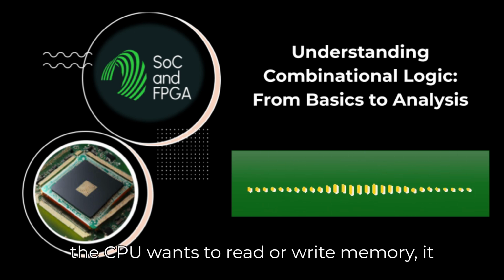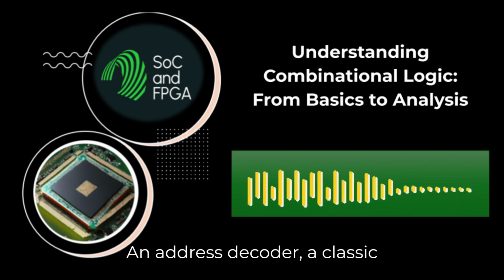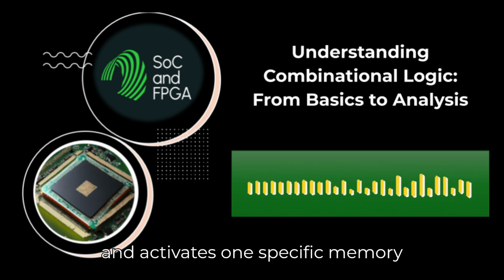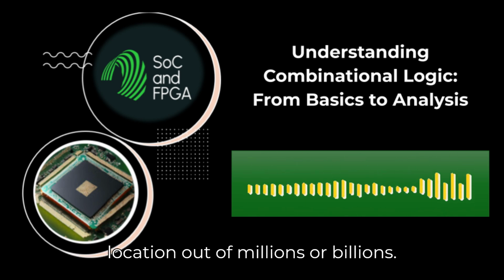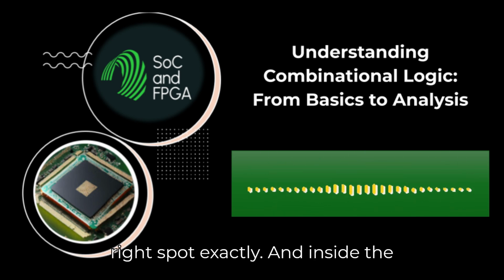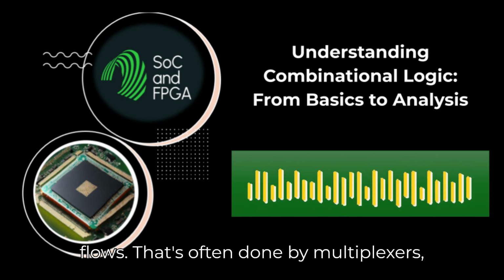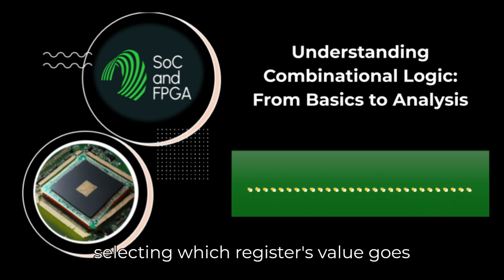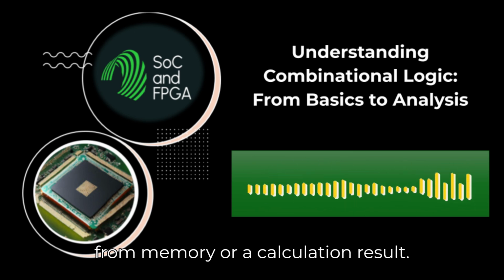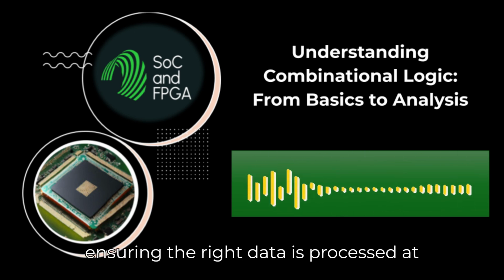And getting data to and from memory. When the CPU wants to read or write memory, it puts a binary address on the address bus. An address decoder, a classic combinational circuit, takes that address and activates one specific memory location out of millions or billions. Purely combinational. Pointing to the right spot. Exactly. And inside the processor itself, managing where data flows, that's often done by multiplexers. The data selectors we talked about. Yep, selecting which register's value goes into the ALU, or whether the data comes from memory or a calculation result. MUXs are constantly directing traffic, ensuring the right data is processed at the right time.